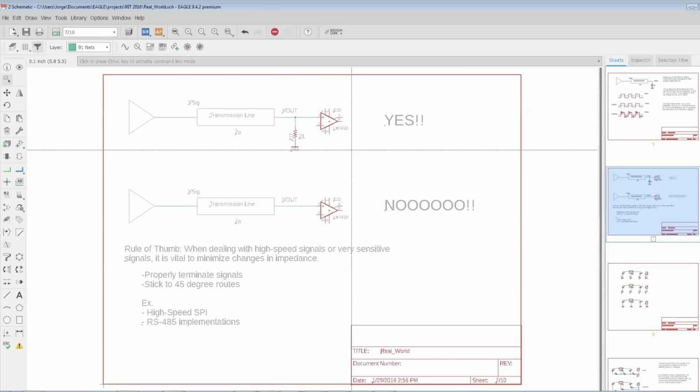So you can imagine that in a situation like this, if you have a lot of signals and a lot of traces, there's going to be current that overlaps or runs through each other, and that's going to create noise. It's going to create additional issues. These are things that you have to become very aware of when dealing with the high-speed regime.